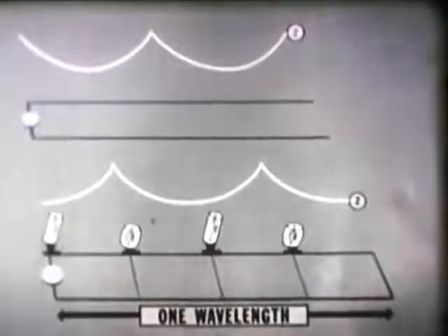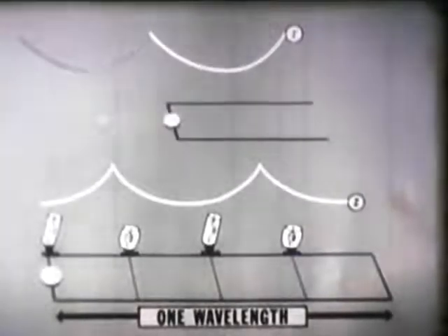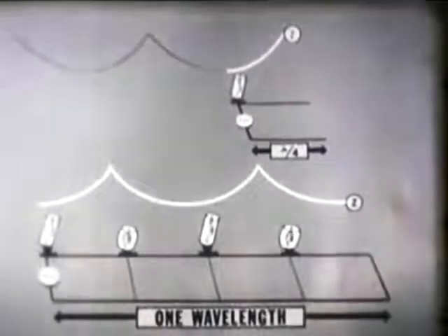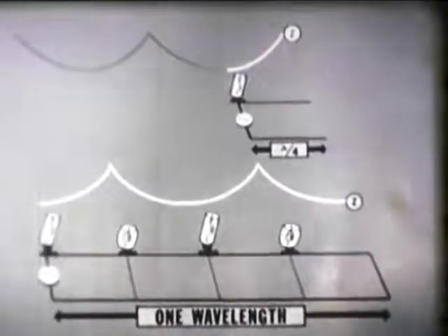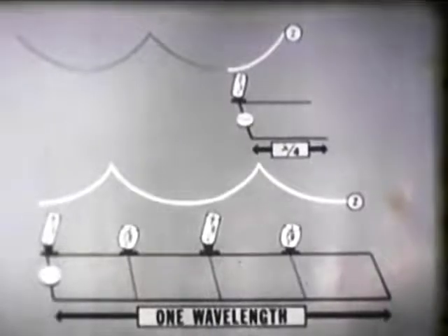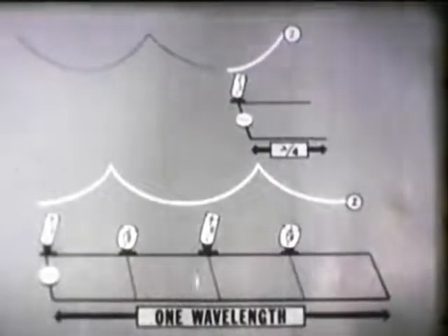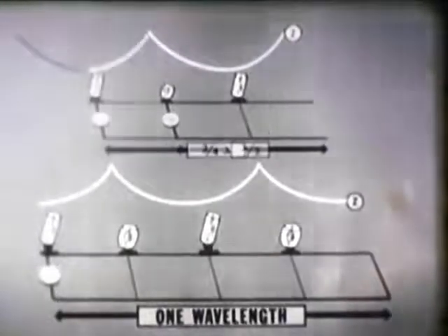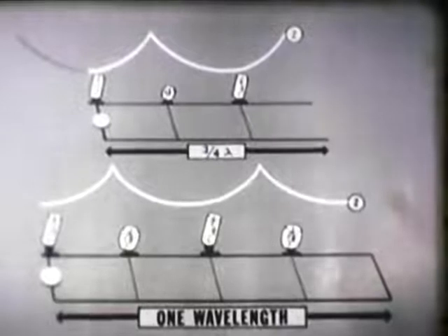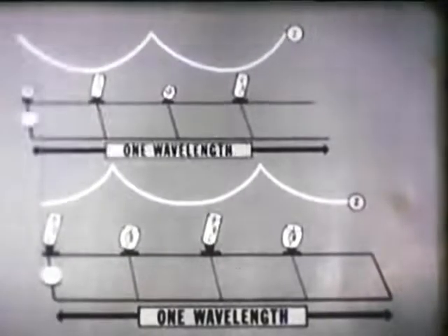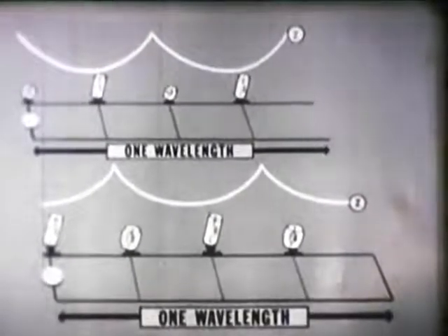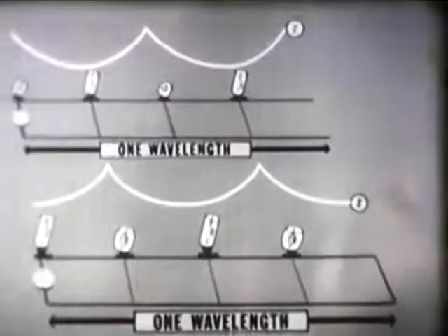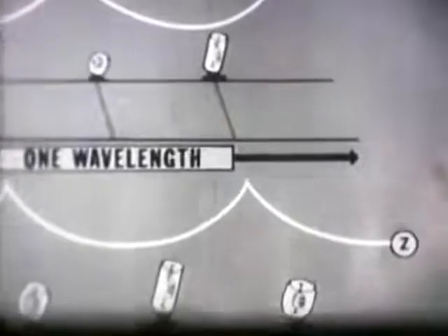The behavior of our open line can be investigated in the same manner. At the 1/4 wavelength point, the generator sees a condition of minimum impedance. This circuit can then be considered a series resonant circuit. Each time a 1/4 wavelength is added to the circuit, the condition changes. Thus, open and closed end lines can be used as parallel or series resonant circuits, according to the length of line used. Because of this facility, they are known as resonant lines or tuned lines.